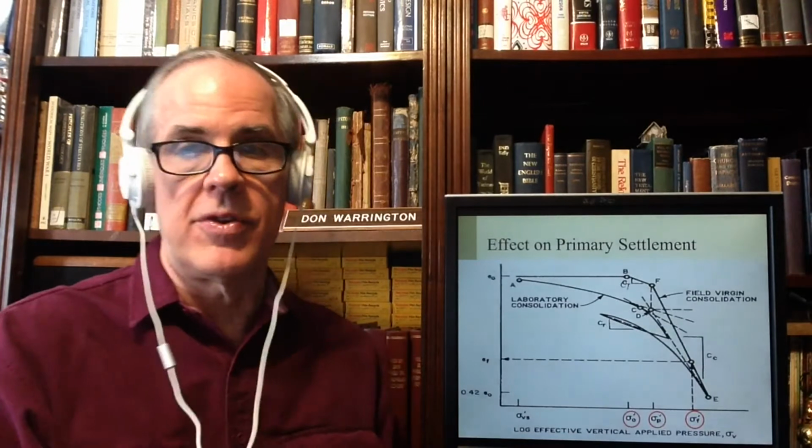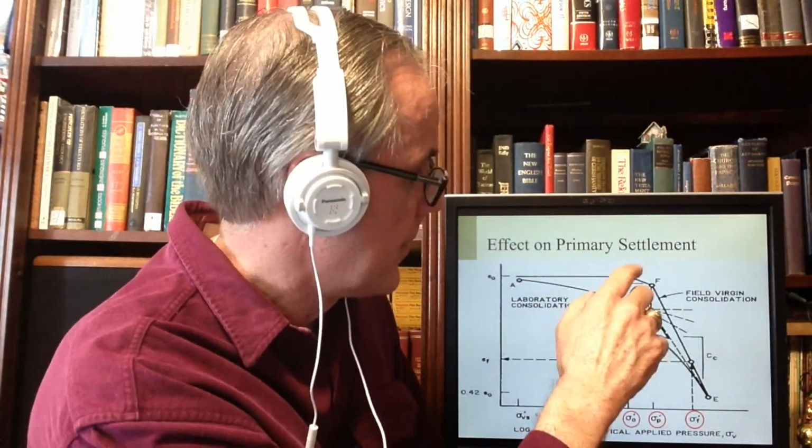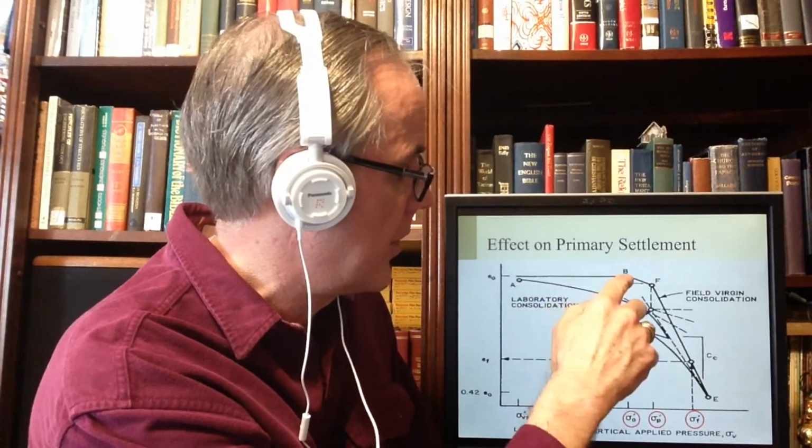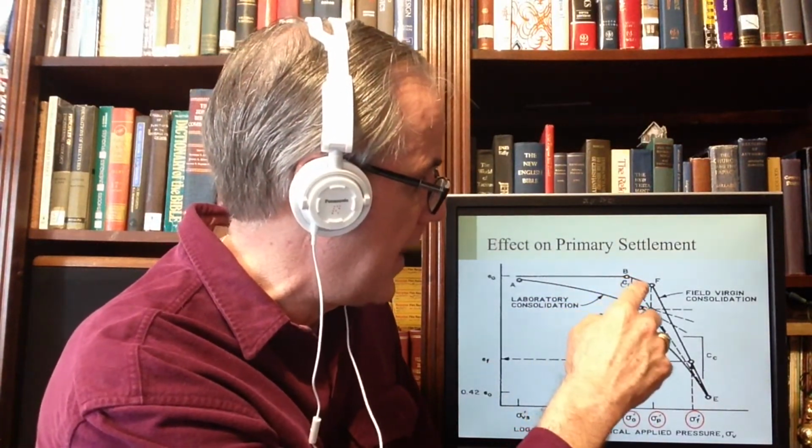The problem with it, and the effect on primary settlement: I've taken this presentation from my past presentations on the subject. Your book also has one, so look at it too, in your Soils and Foundations manual. Instead of having one knee in the curve, they have 2 knees in the curve. From A up to B, which is the current effective stress, and then they come down.